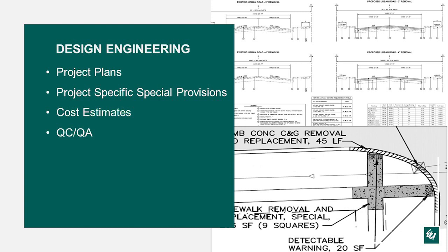One of the most important parts of these projects is the cost estimate, making sure that you have enough material in there so that it reduces the amount of change orders in the field or extras that come about. We also like to put in a little bit of fluff, especially on asphalt, for loss of material. Also, sometimes add a couple of sidewalk squares, because when you're doing the ADA stuff, sometimes you end up having to replace more squares than you thought you would.